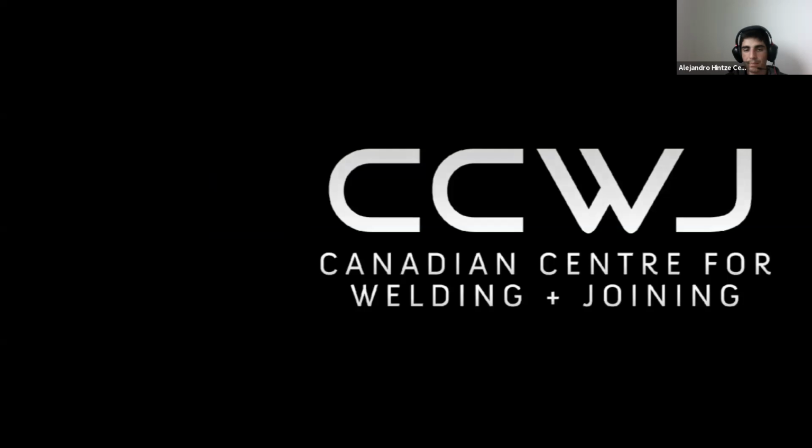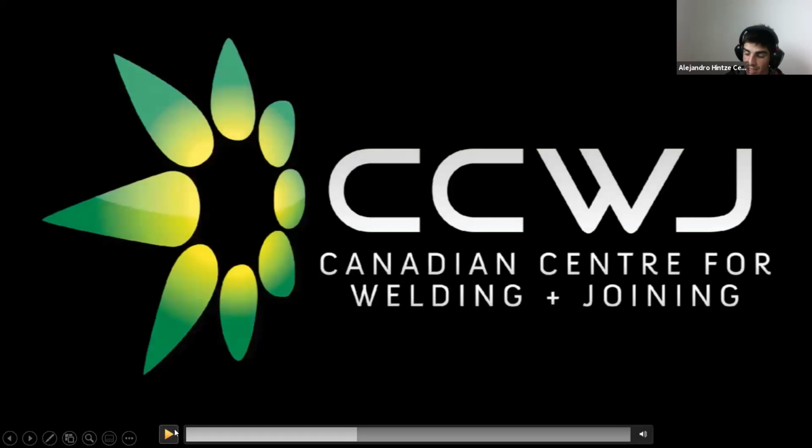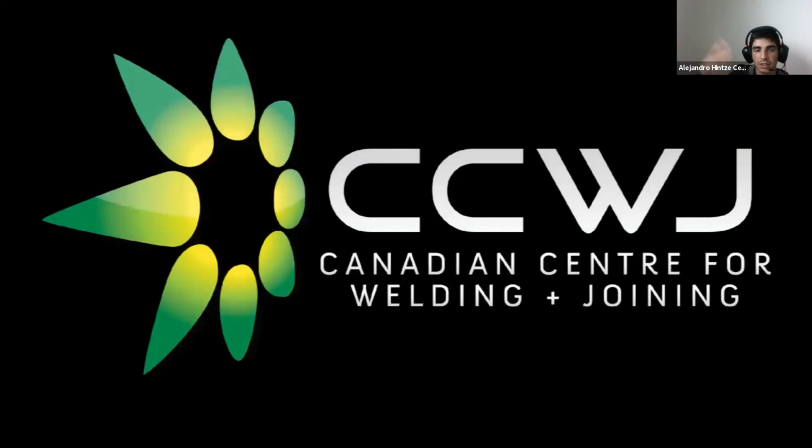So in this case, the background current is around 60 amps, and the peak current goes all the way up to like 300 amps. So that complex current wave that we saw in the lectures, those are the peak and background values that we are managing in this case.